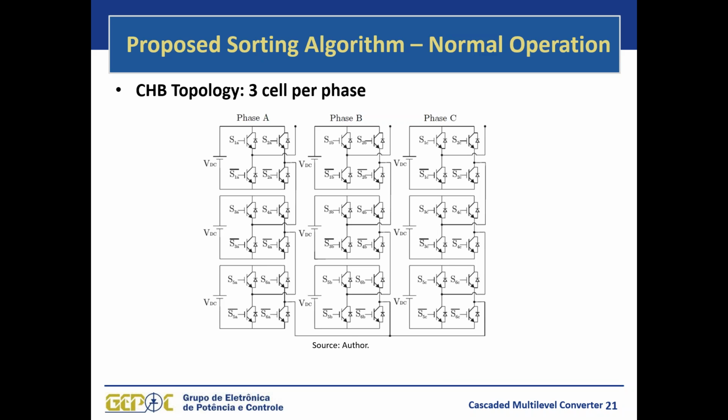So we have the 3 phases, and an important aspect of the modulation that we are going to present is that each one of the phases is treated separately. So we can modulate phase A, phase B, and phase C in a separate way that makes the modulation easier to implement.